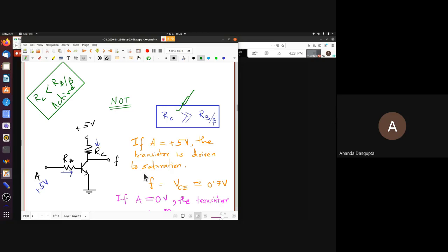What you want to ensure is the circuit will go into saturation, and no amount of small changes in the circuit's components will change that. So it's not only driven to saturation, it's driven to what is called hard saturation. This means the voltage between collector and emitter is actually smaller than the voltage between base and emitter. So VCE would typically be smaller than 0.7 volts.